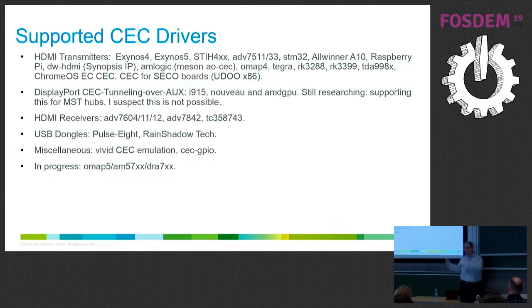I have a status document, I'll have a link at the end, where I have a list of known good working adapters, because a lot of them say they support CEC, but they haven't hooked up the CEC pin. So from the point of view of a laptop, you think, hey, I have CEC. And there is CEC, the firmware, the chip does it, except I didn't hook up the pin. And there's obviously for me no way to detect that.